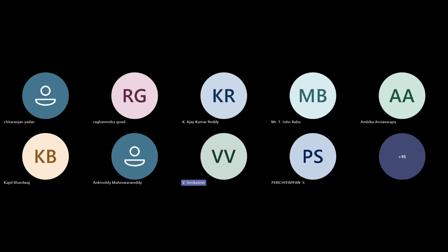We haven't mixed silk fibroin with the water. Silk fibroin is a different material, and the material used to print the bone scaffold is a different material. Just imagine, sir, if you need a product with 10 layers of thickness: after completion of printing the first layer, we covered the first layer with the silk layer, I mean silk fiber. After that, we printed the second layer, and the second layer was covered with the silk fiber, and then we printed the third layer. Likewise, after completion of each and every layer, the previous layer was covered with the respective silk fiber materials for improving the biocompatibility and biological properties.